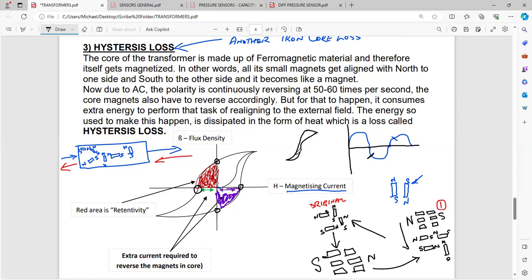Again, how do you reduce your hysteresis loss? By having cold rolled steel rather than soft iron core. You will never get something where you will not have this curve. Ideal would be a complete straight line, isn't it? Where no energy is lost. As you're coming down to zero over here, everything is changing to this. And as you're coming down to zero over here, everything is changing.